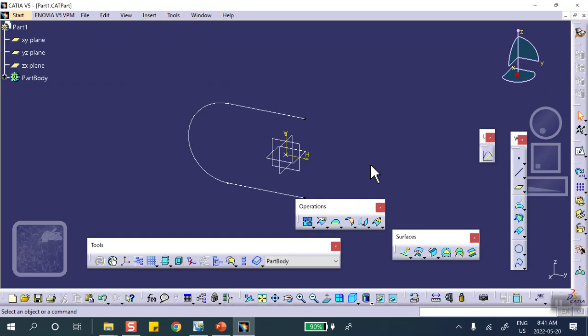The way the orientation point works is that from that point, you drop a perpendicular to the curve, for example, the bottom edge or the top edge, or the circle. You drop a perpendicular. That is your y-axis. X is along the beam, and Z is perpendicular to both of them. Knowing this removes that uncertainty and randomness out of it. In this case, the only restriction is that this point cannot be on this curve or on the continuation of it, because if you drop a perpendicular from that point to the curve that it sits on, you're going to have a problem. That's the only restriction. Exit.